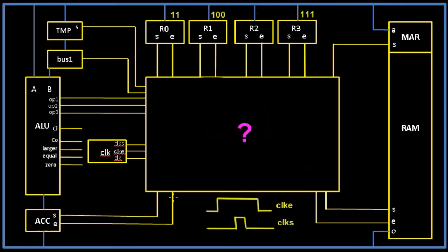And then the enable's got to go high in order to put that number 7 onto the bus, and the number 7 goes onto the bus. And then we come along here and we've got to put the set high on R3, so that number 7 gets read in here. And then the set goes low, so that number 7 is held within this register. And then finally the enable goes low, and that's us worked through our full process of adding 2 numbers.